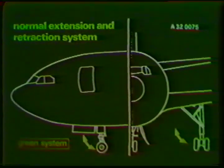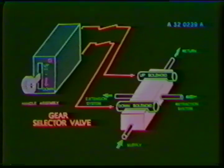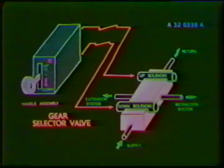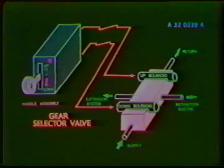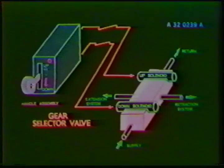Now, in more detail, the normal system is powered by the green hydraulic system for extension and retraction. The gear handle is provided with 3 positions: up, neutral, and down. The up and down signals are electrically transmitted to a gear selector valve controlling extension and retraction. When the handle is moved from one position to the other, a sequence is started. Doors open, gear unlocks and moves, and doors close.